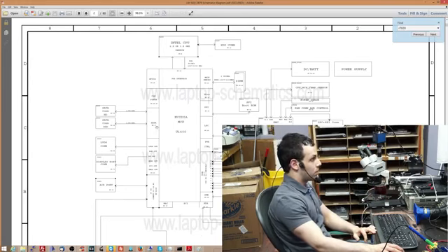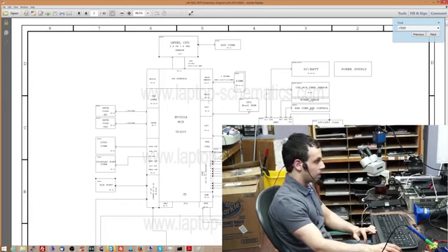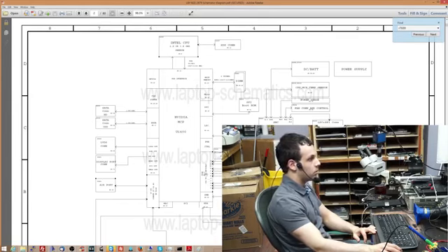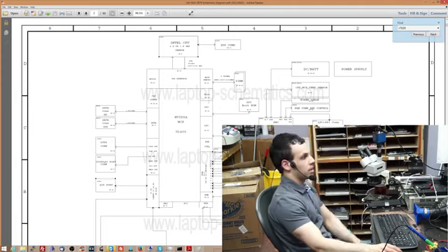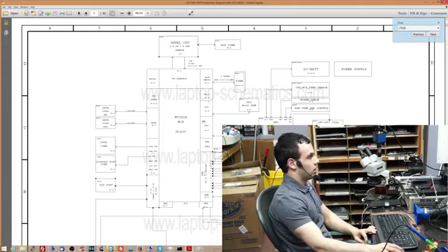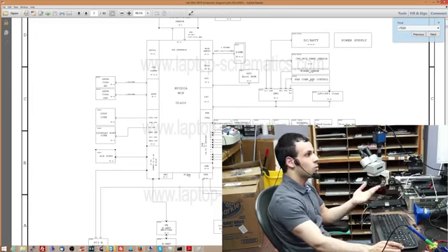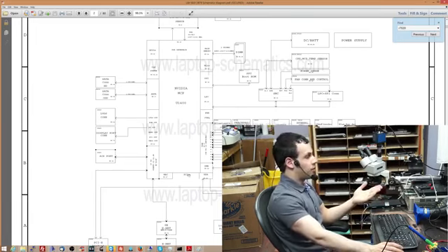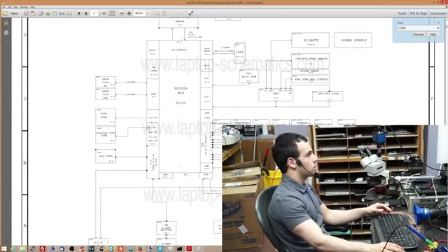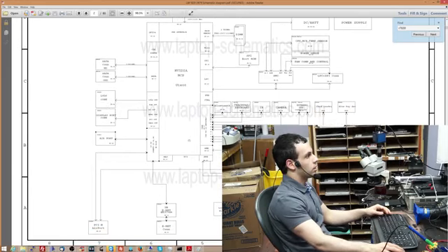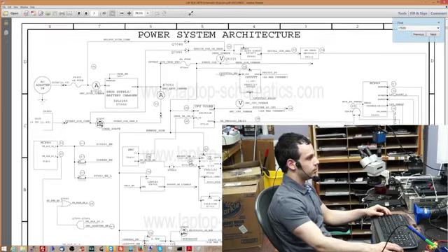This handles serial ATA. This handles interfacing with the main memory. This handles PCI Express lanes. This handles USB, Bluetooth, trackpad, keyboard, your webcam, your external USB connectors, your USB card reader. It controls power for a chip. It sends out signals that control power chips. It communicates with the SMC. It's much more than a simple graphics chip, but people call it the video chip because usually they're clueless. Video makes up a very small portion of what this thing actually does.